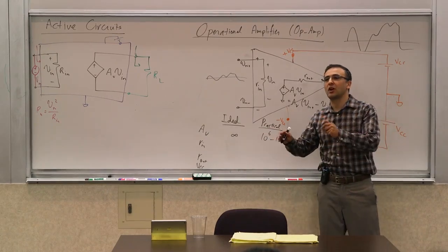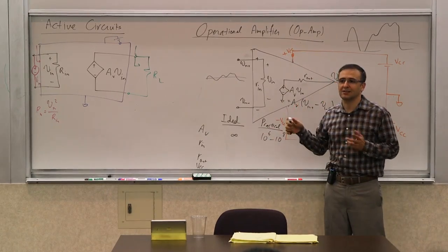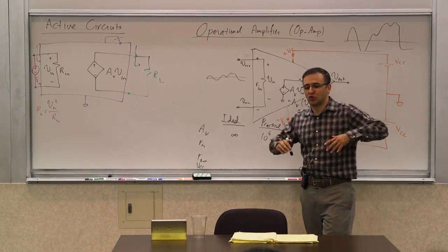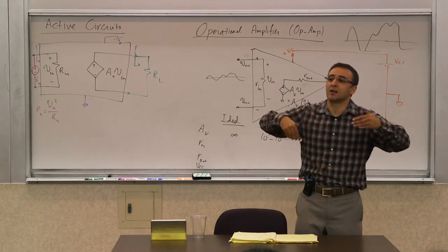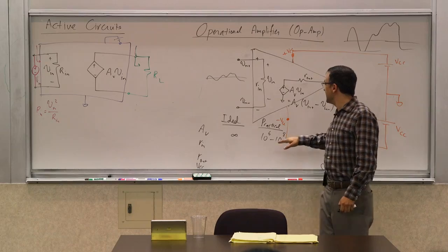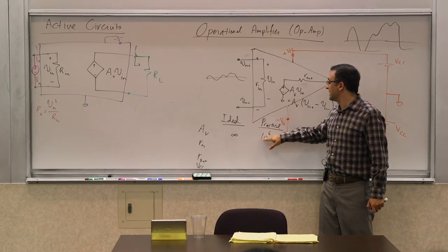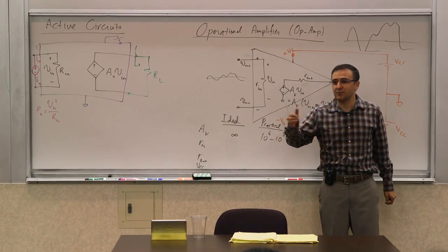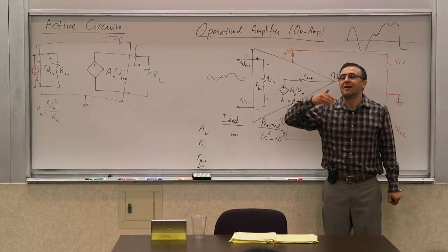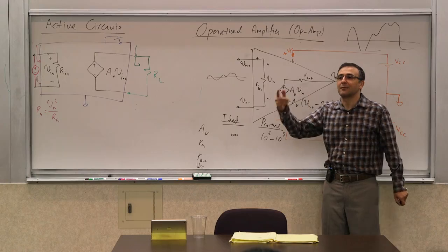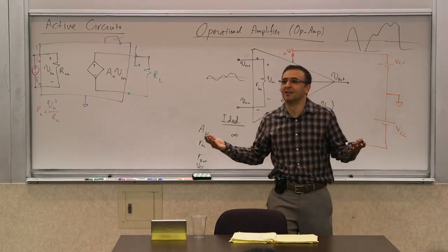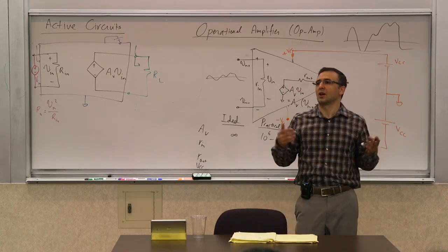This is limited by trying to maintain the stability of the op-amp. And again, that's not something that we have talked about. We'll talk a little bit about stability later on in more general terms. But that's analyzed when you get into an actual op-amp design class, where you see that to get more gain, you need to cascade more stages. And when you cascade more stages, each stage has its own dynamics. And when you use those in feedback, it can produce instability that can show up as the system, instead of amplifying, becoming an oscillator. So those kinds of things can happen.